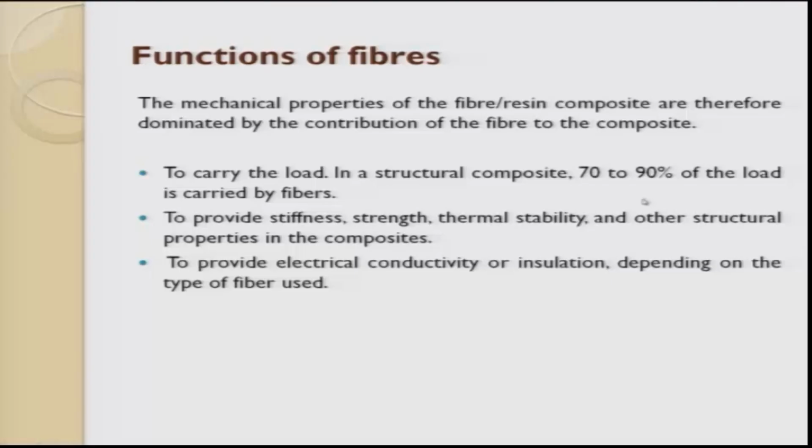The next thing is it provides the required stiffness, strength, thermal stability and other structural properties of a composite. It can also provide electrical conductivity or insulation depending upon the choice of fiber. So in a nutshell, the function of a fiber decides the mechanical property of the given composite.